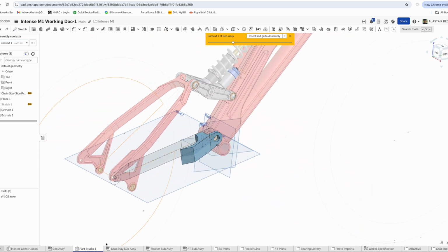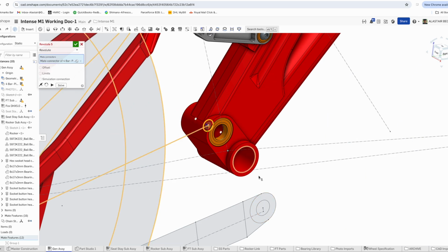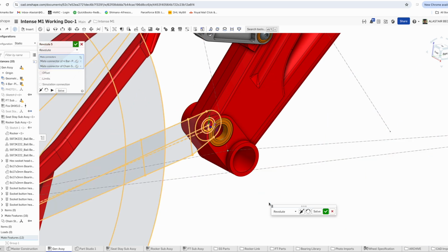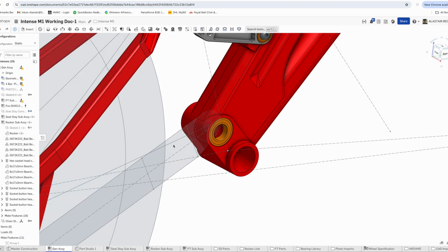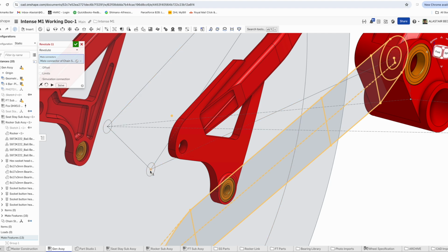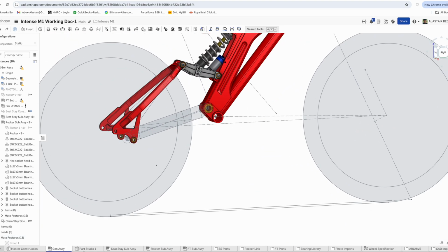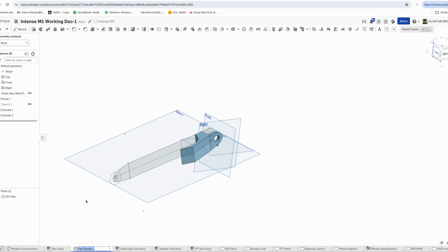In some uses, it works really well. So we'll stick that into a new chainstay subassembly, and then we'll continue to build off of that for the tube and the rear clevis parts. So again, just making sure that sketch is in there, and that it's mated correctly to the right mate points, and then we can start bringing our chainstay subassembly together with the rest of the parts.